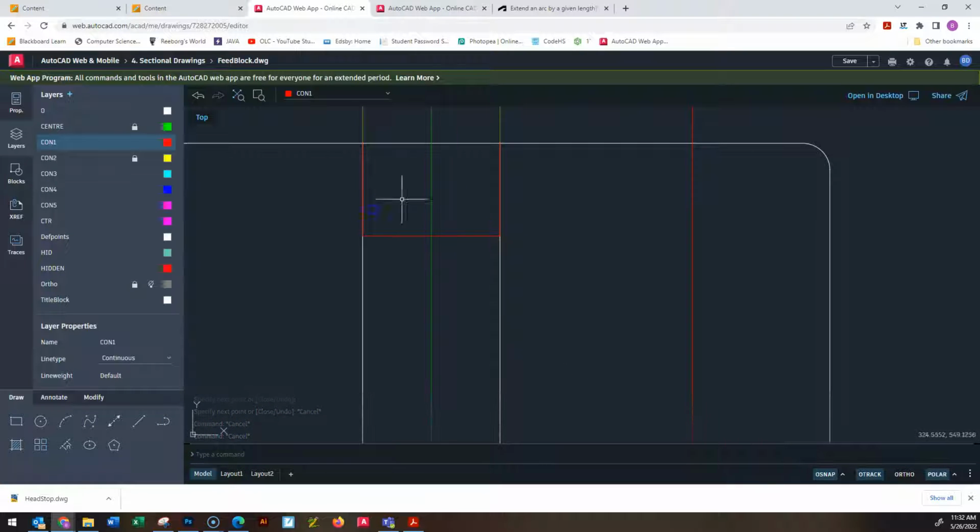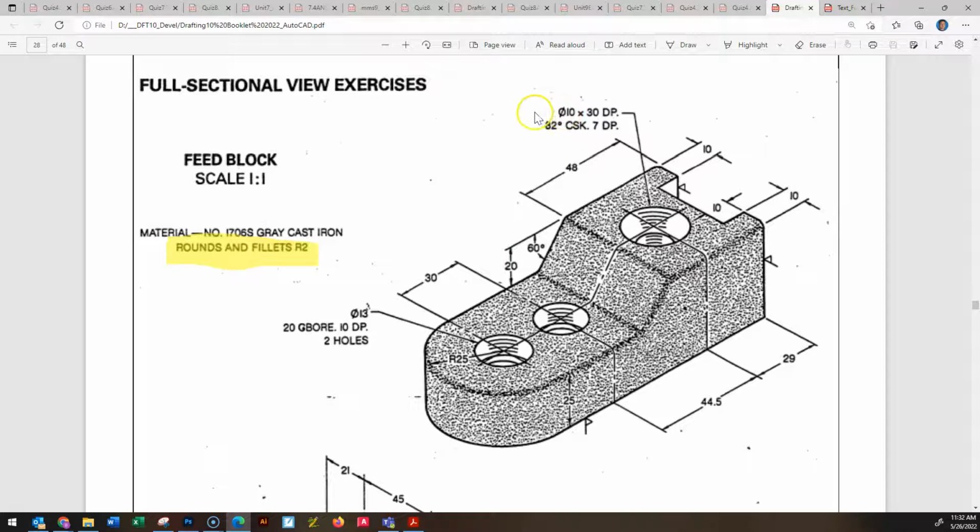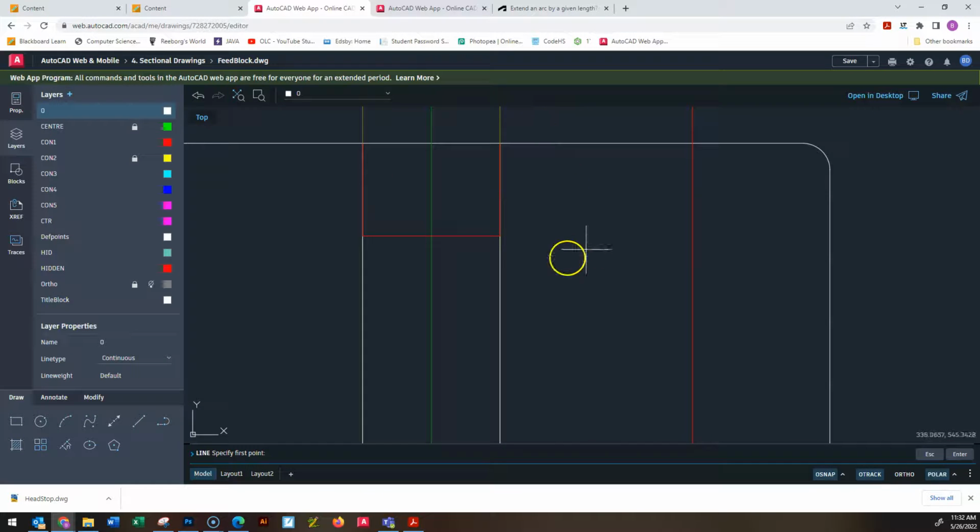And then the last part, because we now understand how to build a countersink at a certain angle. We did all the math before. You know what it is. Now you just need to use that same math every time you see an 82-degree countersink. If you see a different angle of countersink, you're going to have to make sure that you make that interior angle, whatever it is, 80 degrees, 90 degrees. But you're going to see 82 for most of our examples in this class.